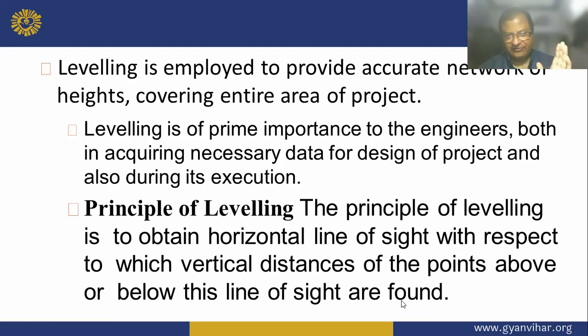The principle of leveling is to obtain a horizontal line of sight with respect to which vertical distances of the points above or below this line of sight are found. Understand?